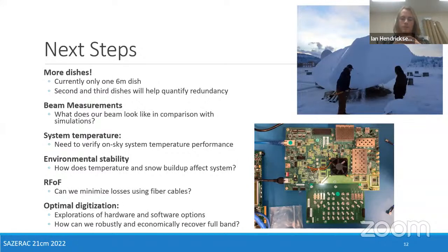And we're achieving these goals with all these different technologies that I outlined today, where we've seen that the dish is sub-millimeter compared to a parabola, and we can see this across multiple dishes. We find that the reflection coefficient is less than around -10 dB for the feed, as well as a 50% aperture efficiency, which is difficult to maintain across a wide bandwidth. And the LNA has a nominal noise temperature of around 10 to 20 Kelvin. And since this is the dominant source of noise within the system, it's really important to keep this low.